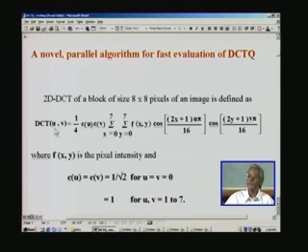That means you have a total combination of 64 here. Because 0 through 7 is 8, so 8 into 8, so totally you can have 64 DCT values; this is called a DCT coefficient. If you take one block of image consisting of 8 by 8 pixels, out come 64 coefficients here, and mind you, there is no direct relationship between each of these pixels. You can't say one pixel is related to one coefficient.